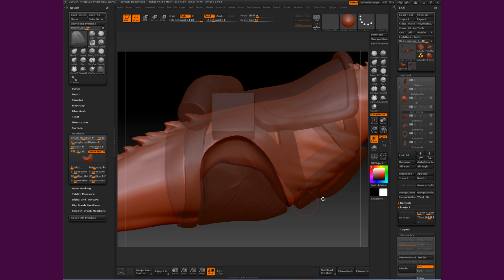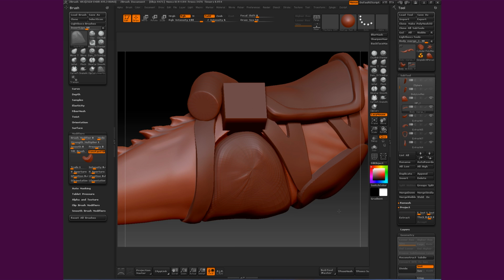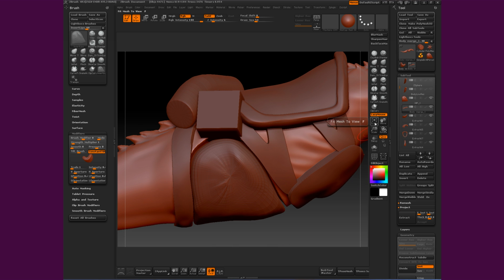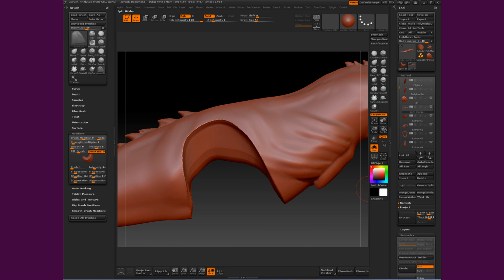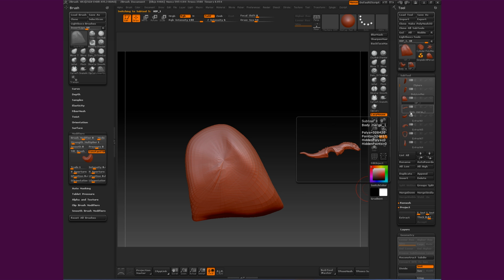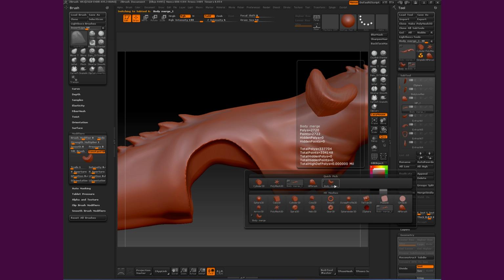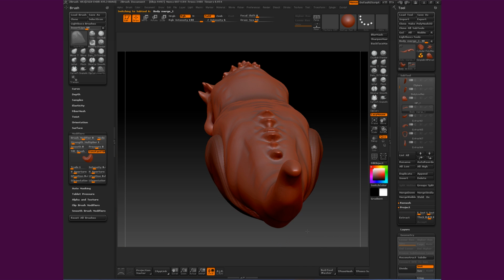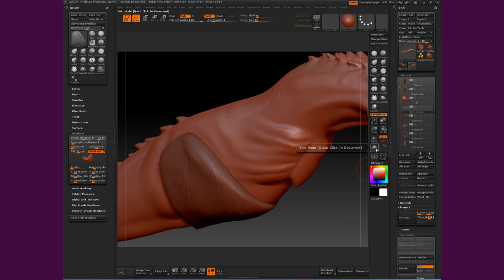As you can see the ghosted image there. So let's turn off transparency. It's not right. You see how it's not exactly the same size as your original? We probably could work on that, but let's go to solo so you can see what it looks like. There's our soloed object. So now all we have to do is take off solo. We'll hide this hip, go back to our extracted piece, and then hit append, and then go to this body merge, and bam, you have an exact piece that fits the extraction that you made.